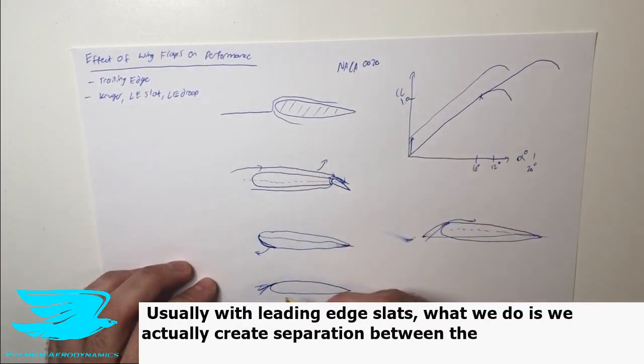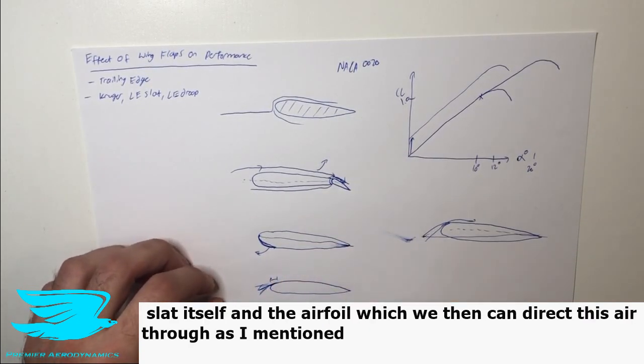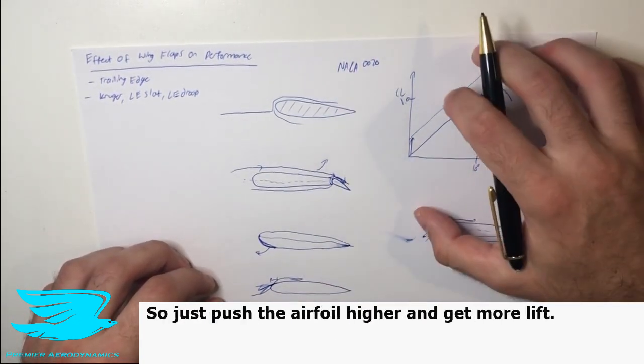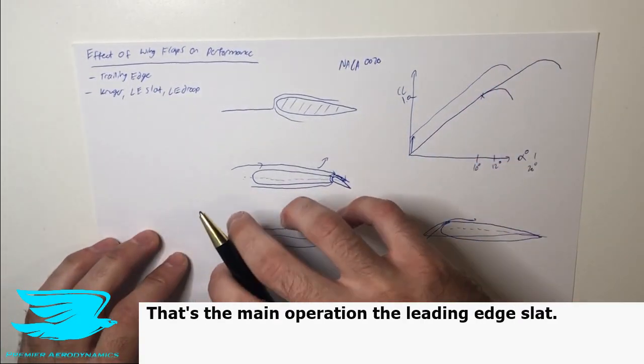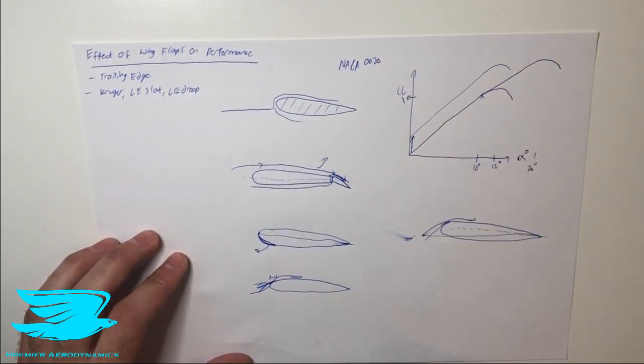Usually with leading edge slats, what we do is we actually create a separation point between the slat itself and the rest of the airfoil, which we then can shoot this air through, as I mentioned here, and keep the flow attached at a high angle of attack so we can push the airfoil higher and get more lift. That's the main operation of the leading edge slat. Again, we can always extend it further down and increase the camber, but that's not necessarily the case.